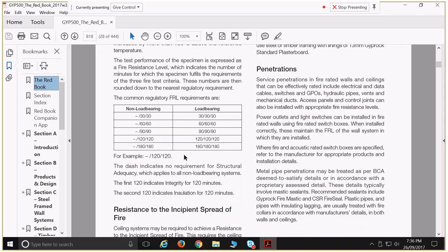So our fire rated walls have to meet certain criteria. For assignment 3, you're going to have to go through that process of saying, what building classification is this? What fire resistance category does it come under, A, B, or C? And then given that, what fire resistance level am I going to need for a fire separation wall? You're going to have to go through the National Construction Code to do that. It's fairly simple. We can go through that, and you'll arrive at one of these figures.